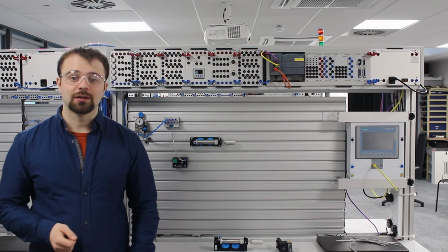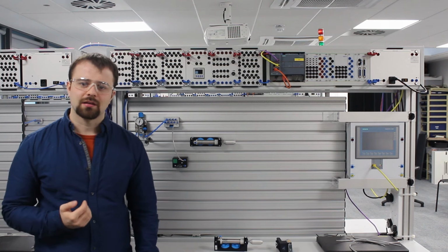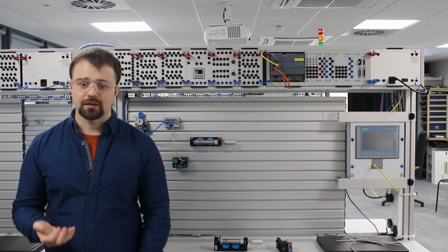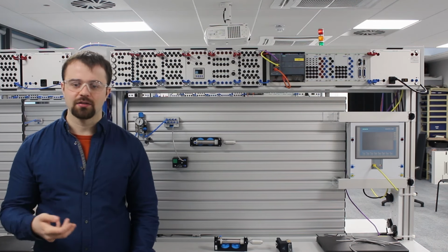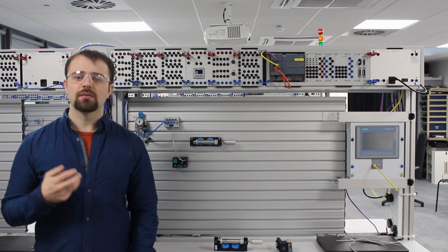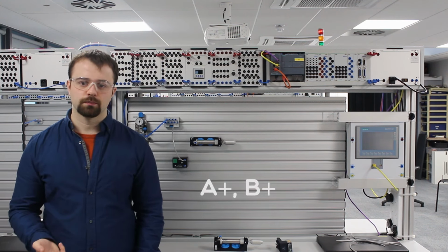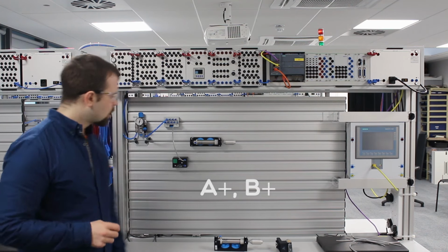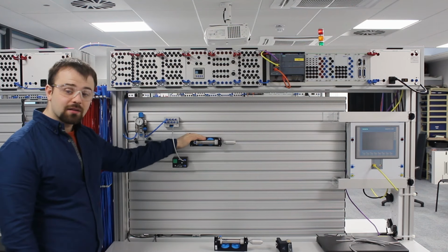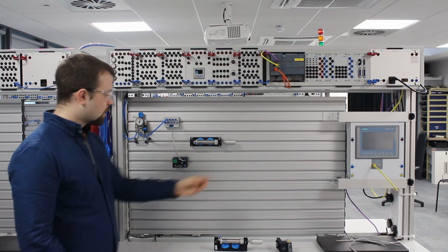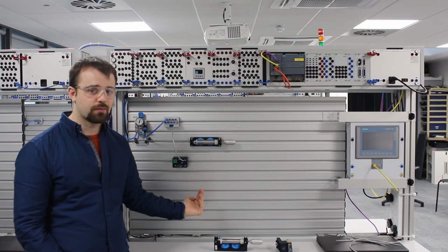Now we're going to start to have a little look at pneumatic sequencing. So far all we've done really is push a button and get a cylinder to move forward, but a lot of time in pneumatic problems you get sequences such as A+, B+, B-, A-. So we're going to look at about the most simple sequence we can to start with, which would be A+, B+. So what do I mean by A+? Well, if we take this cylinder to be cylinder A, at the moment it's in the A- position. As it moves forward, it becomes A+ before moving back again to A-.